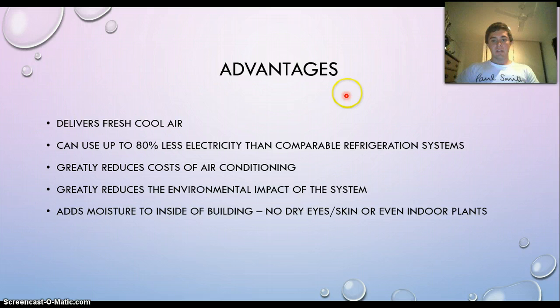The advantages of having an evaporative cooling system are that it delivers fresh cool air, because as the air travels through the wet pads, it's basically just general air from outside, and the wet pads also help recycle and filter the air. One of the biggest advantages of the system is that it uses up to 80% less electricity than comparable refrigeration systems, which are the most common air conditioning systems.